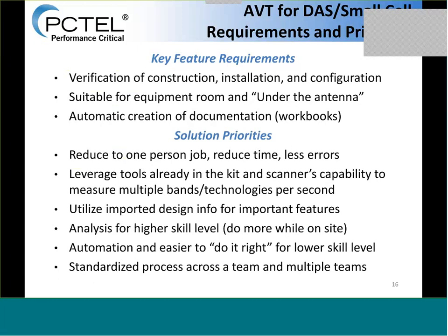Something like that. So we were asked, can you help find a tool that will be fit to that type of work? We want to be able to verify the construction, installation, configuration. We want to be able to have something that's useful in the coverage area as you're standing at the antenna, but something that will also work when you're in the equipment room. So you want to be able to address both of those types of work functions, and something that automatically creates documentation of the style that we're used to doing. So creating an Excel spreadsheet that has the right types of values, information about the network plan, and the corresponding measurements that were made.